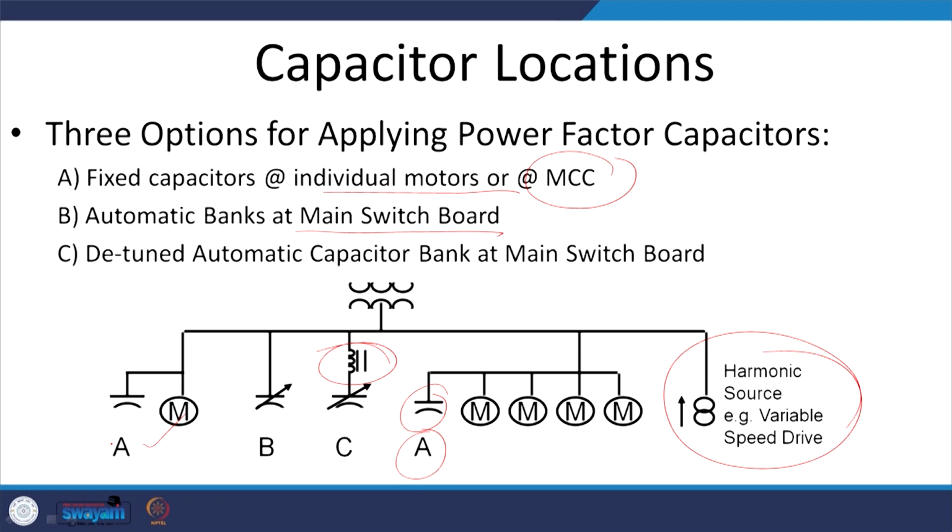Each has its own advantage and disadvantage, which you have understood from our discussions. Generally, detuning is used so that it does not have a resonance with your power supply. Since A is fixed, there is no point of control, so sometimes it may take a capacitive bar also.